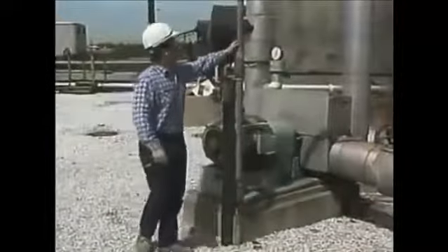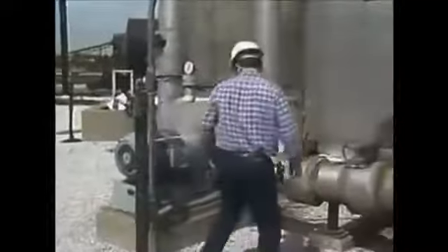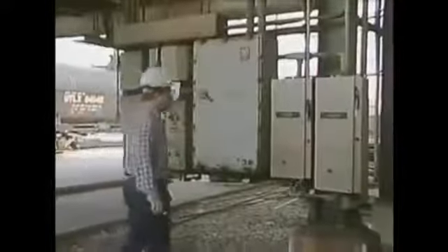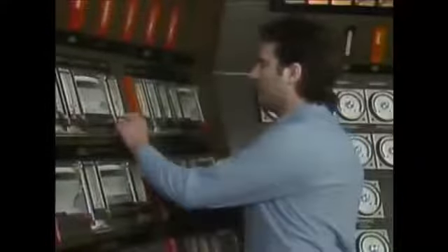Some motors may have a grounding strap or ground wire that helps prevent electric shock hazards. It should be checked to make sure that there is a secure connection between the motor and ground. In addition, the motor should be inspected carefully for anything out of the ordinary, such as loose or missing components. The motor controller should be checked to make sure that it's energized and ready for the motor to be started. Depending on your facility's procedures, you may need to notify the control room operator before the motor is started. When all checks are complete, the motor can be started by pressing its start button.